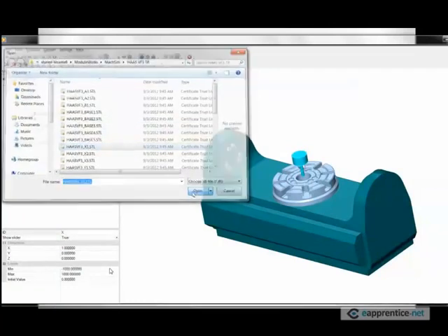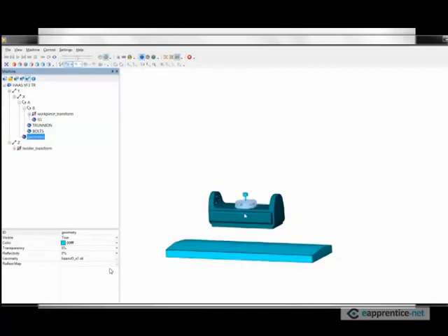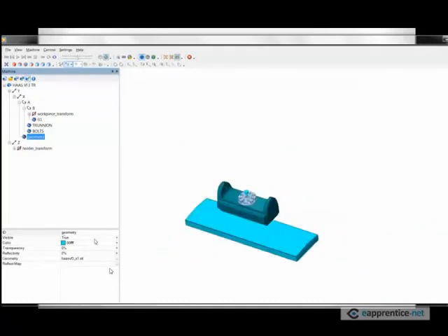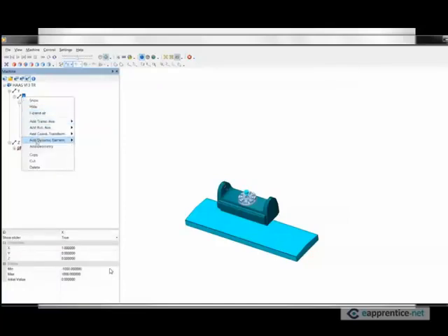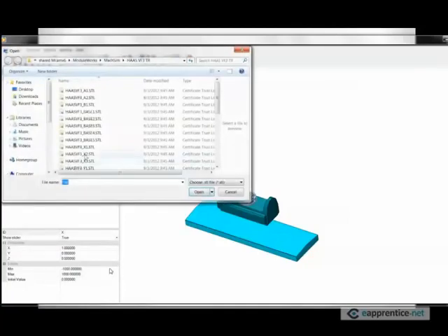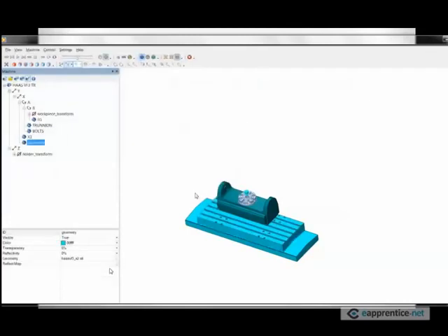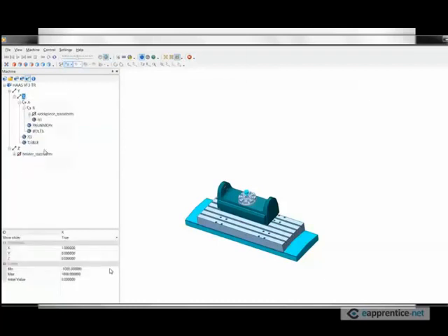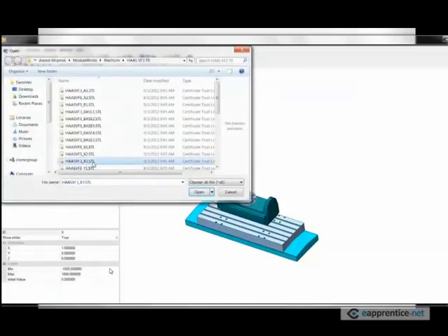Now here we are just adding the x-axis, and this is actually one of the ways on the x-axis. And all these models come in a correct position in the way you model it. By the way, when you model the machine, you have to have every axis sitting at 0. So x, y, even the z-axis is at 0. So the spindle of the machine z-axis will actually sit on the intersection of the dual rotary.